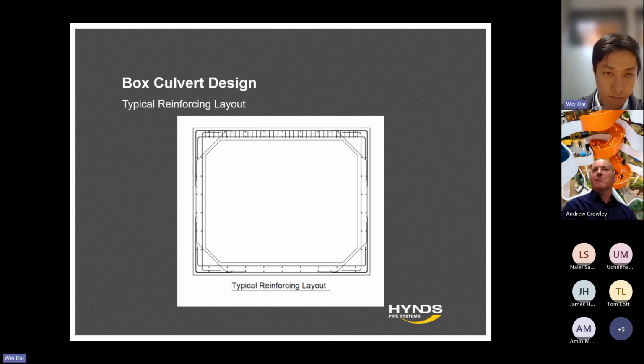So we have the reinforcing detail for your box culvert in the end. This is a typical reinforcing layout for box culverts. As you can see, on the external face we have one layer of reinforcing and another layer on the internal face. Some chamfer bars at the corners, and longitudinal bars running through the culvert unit along the water flow direction, or the longitudinal direction of the box culvert line.